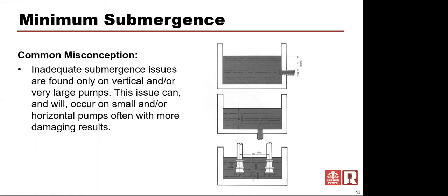So a 9-inch radius or a 12-inch radius, whatever. And it's a half circle that's welded to this tank above this line. And what happens is the apparent velocity at the edge of that plate is much lower, and therefore it doesn't create that vortex that comes down into the pump or into the intake, because we've created a shelf above it that the apparent velocity at the edge of that plate is low enough.